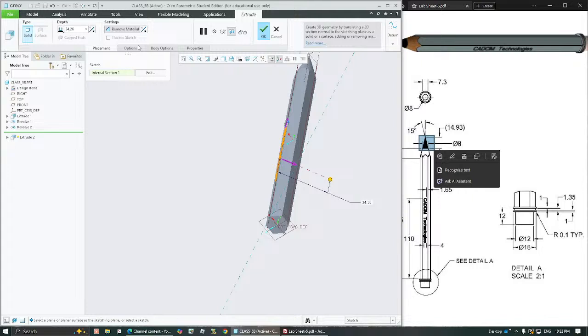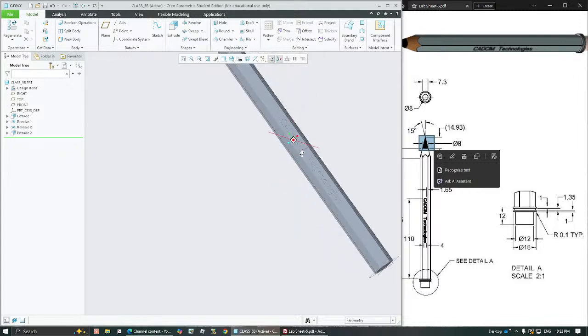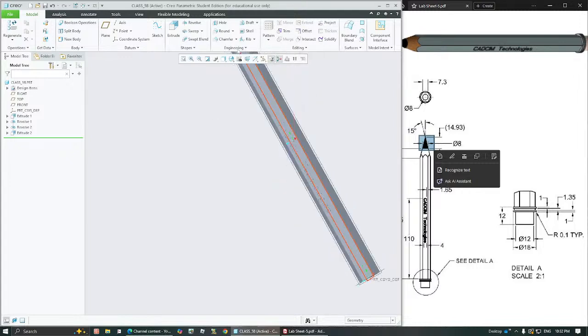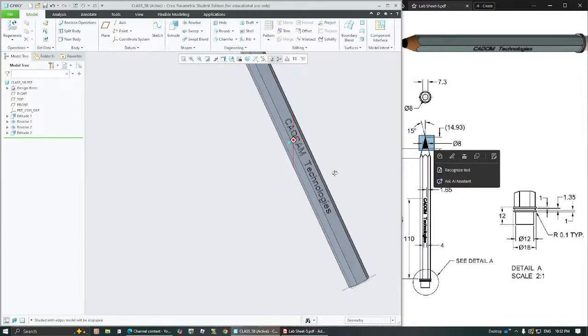and we need to choose how deeply it is to be cut. The depth of this is not clearly given. Let's go ahead and choose something small enough, 0.5 or something, and click OK. So you can see this has got created. If we choose the edged view, you can see, we'll be able to see the edges as well. So this is the thing created.